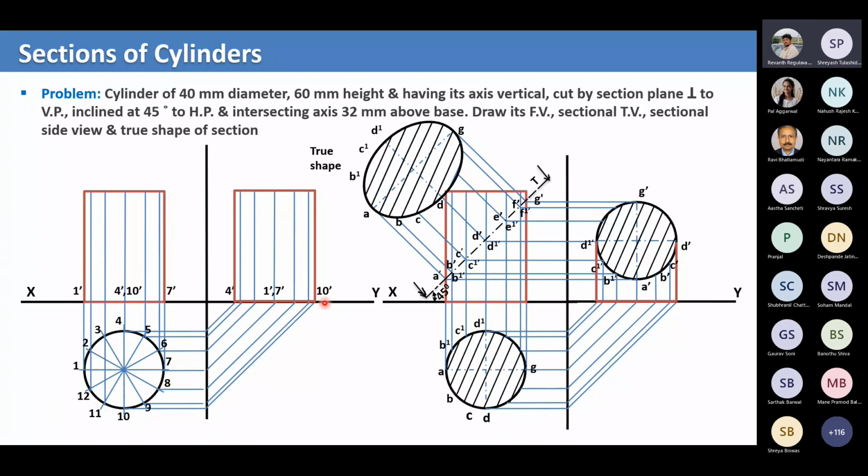First thing you need to do is labeling. Now there is a section like this. So this is the section. And now what you have to do is label each and every intersection of our sectional plane and the generator. So let us say these are the lines, generators. Why am I calling them generators? Because in a cone, the slant height is called a generator. You have one generator and you rotate it about the axis, you get the cone. So that's why it's called a generator. Let us call these also generators.